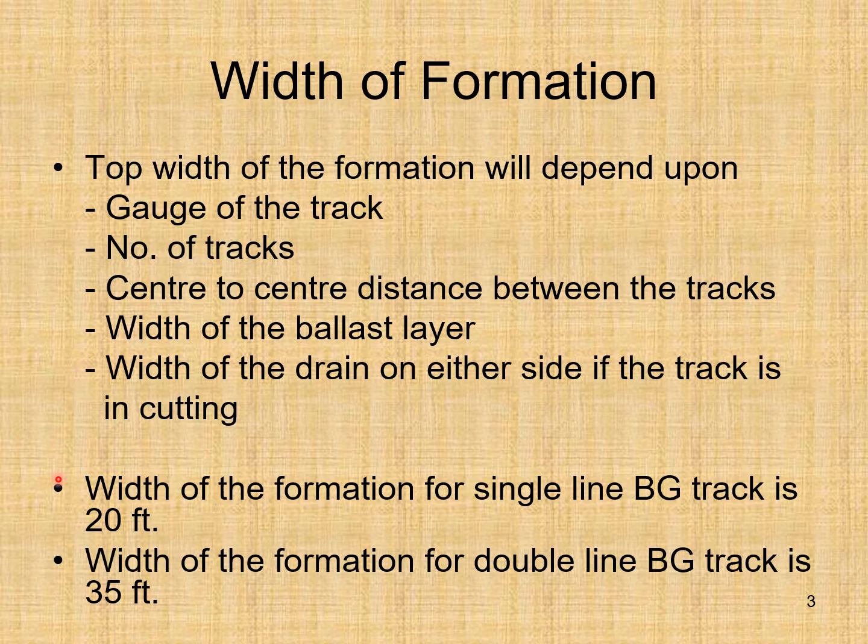There are some important considerations regarding width of formation. Width of the formation for single line broad gauge track is 20 feet, and width of the formation for double line broad gauge track is 35 feet.